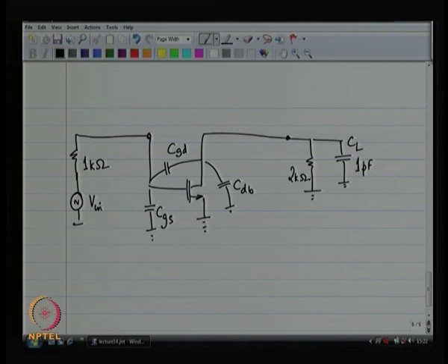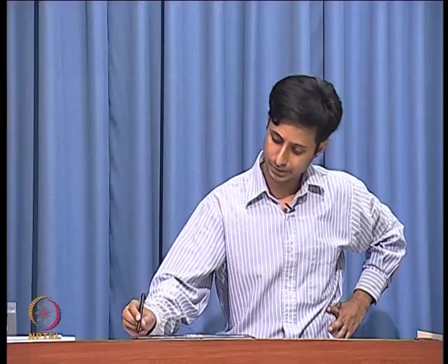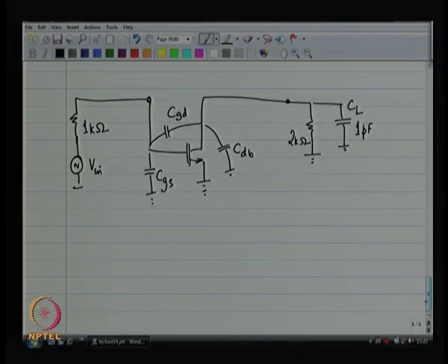All right. So, first step, let us pull out the capacitor. First of all, let us pull out the capacitor CL, okay, and we want to measure the resistance when we pull out CL. So, CL is outside, and we want to measure the resistance looking in over here with respect to ground, but of course, what else? All the other capacitors are nulled, which means all the other capacitors inside are removed.